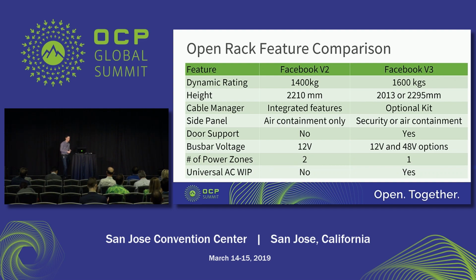And we'll also be going to a universal AC whip interconnect. Unlike V2, where we've got the regionalized interconnect that goes into the bus bar or busway, at least for Facebook, there'll be a single cord that runs down into the back of the power shelf. So we're hoping to standardize that particular interconnect. Depending upon what region you go to, you'll still be able to use the same power shelf and the same interconnect. This will allow us to do away with the PDUs that we currently use, and you'll be able to ship the same rack level configuration to any region of the world.